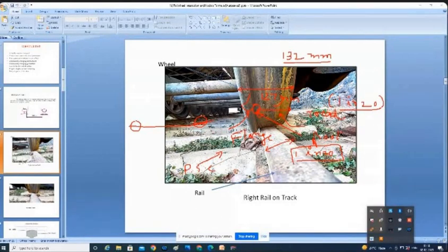So over this, if you make it one horizontal line, automatically 1 in 20 only it will get. That means it is indirectly 1 in 20, directly on the sleeper. Sleeper will be 1 in 20 directly. But rail we are placing over the sleeper. So that is why this rail also will get a 1 in 20 slope. So 1 in 20 on rail table also you will get it. 1 in 20 slope on the tread portion also it will be there. If it is not there 1 in 20, what will happen and all that we will discuss later.